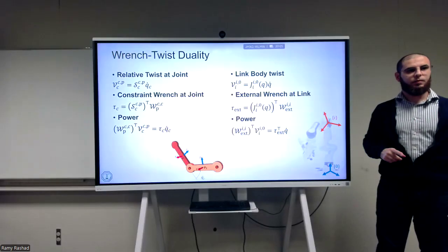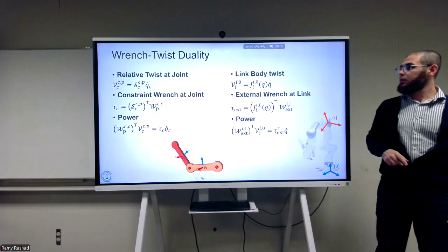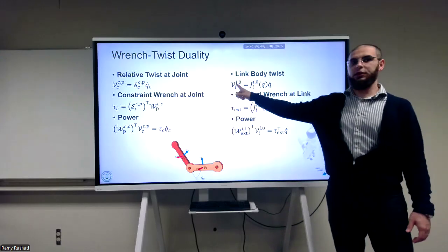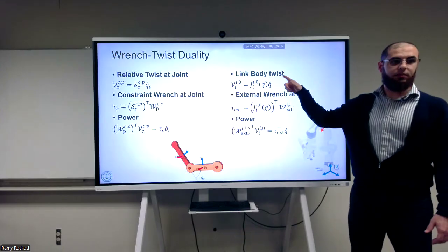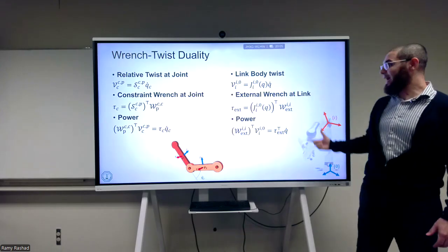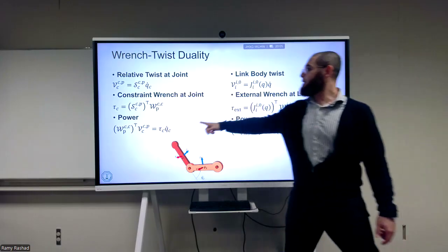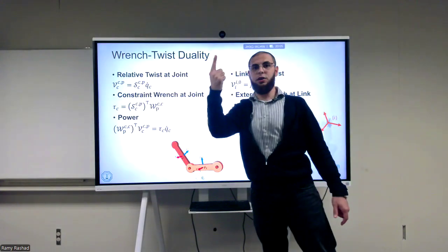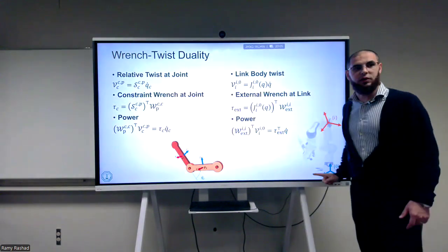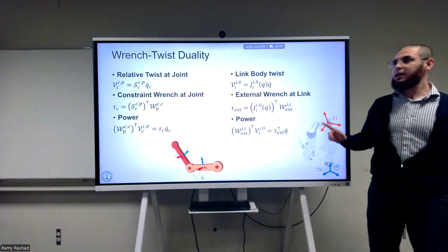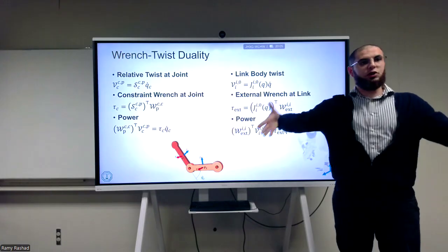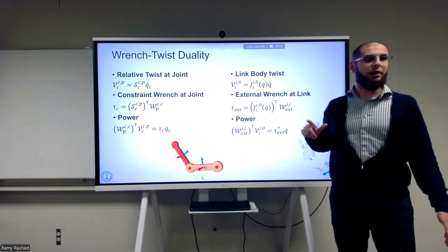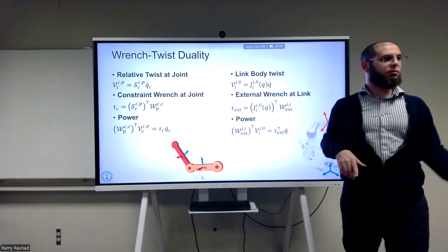Yes. Here, this is a map from Q dot to V. So these are all of the Qs. What you see here on this side is actually a generalization of this. This is only one Q, while these are all of the Qs of the robot. So that's it. And if you remember what was inside of the J, they were actually screws, all of the screws represented in the ith frame. Okay? Yes, sir.